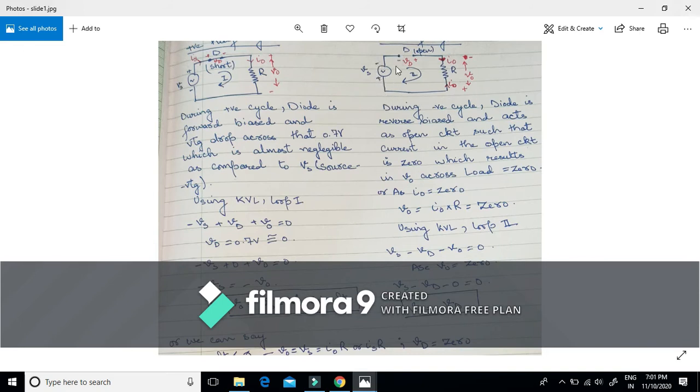Across this diode, since we consider anode with respect to cathode, the anode is negative with respect to cathode, or you can say the cathode is more positive with respect to the anode. Because of that, the diode behaves like an open circuit. The diode is reverse biased, represented here by an open circuit, so in that series path no current flows in the circuit.